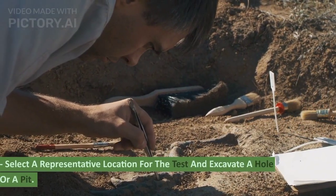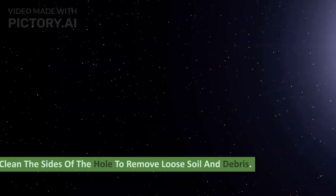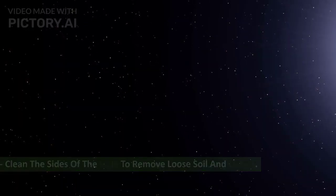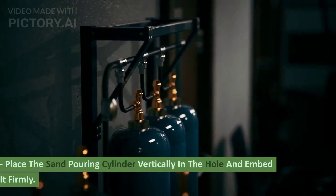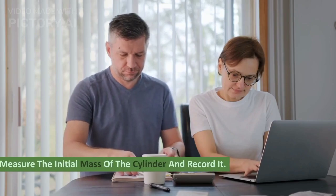3. Field test. Select a representative location for the test and excavate a hole or a pit. Clean the sides of the hole to remove loose soil and debris. Place the sand pouring cylinder vertically in the hole and embed it firmly. Measure the initial mass of the cylinder and record it.